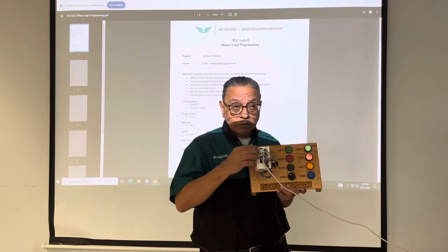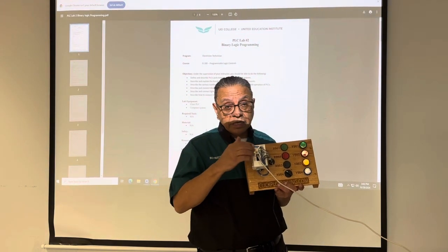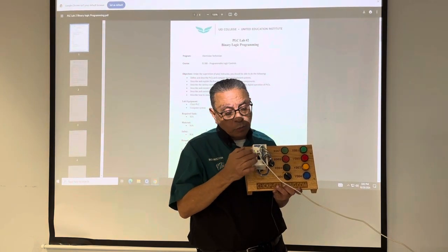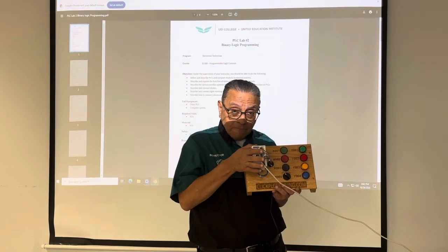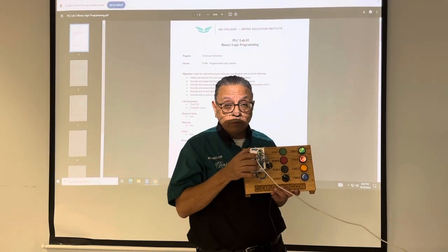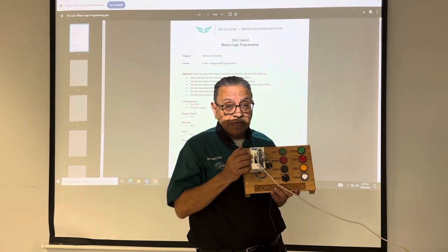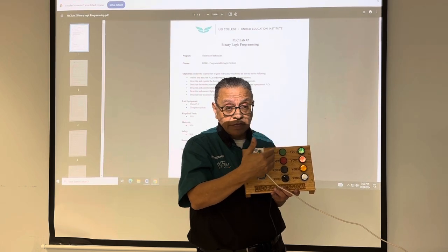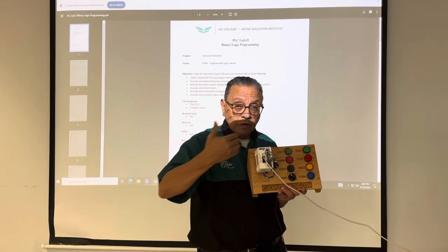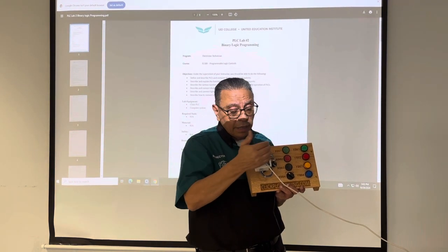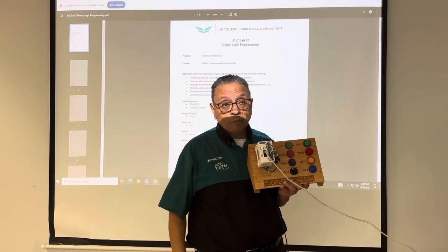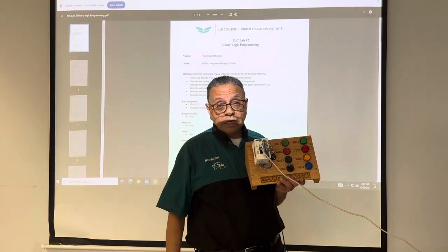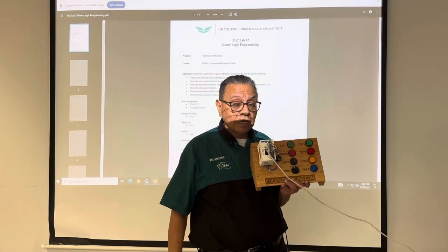It has its own CPU, central processing unit. It has its own memory, random access memory and read-only memory. It has a communication port used by this CPU to get connected with the regular computer system. It has I/O devices, the input and output interfaces. The input interfaces are used to collect information from the external world, and the output interfaces send information to control electrical devices, such as an electrical motor contactor coil or a lighting system contactor coil.